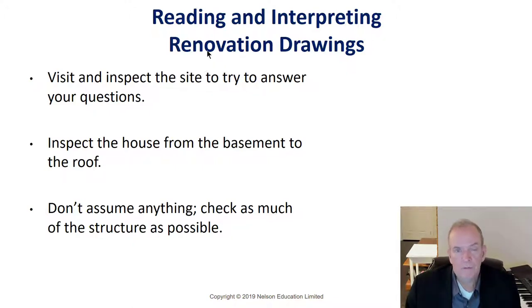You also have to be careful of things such as asbestos. Older houses have a lot of materials that are asbestos related in them. Floor systems, vinyl asbestos tiles in basement, very common. Usually they're 8 by 8, but they could be the 12 by 12. You might have to get them tested. That's a few $100 to get them tested, just to see if it has asbestos. The drywall, the taping compound in the early drywall, it's possible that it could have asbestos in it. A lot of pipe wrap, insulation, things of that nature. Lots of opportunities for these things.